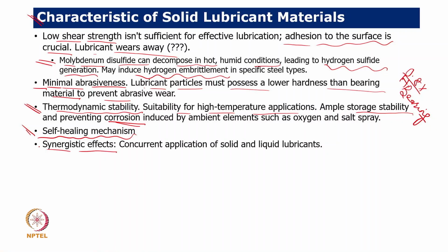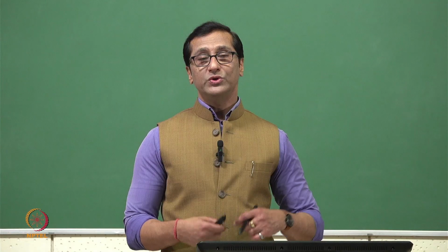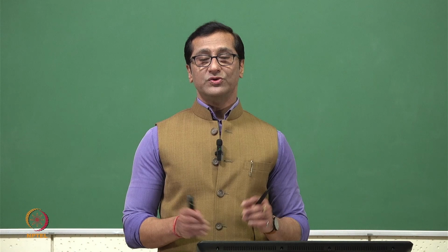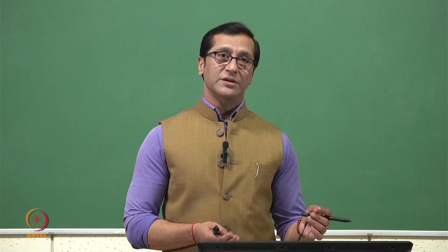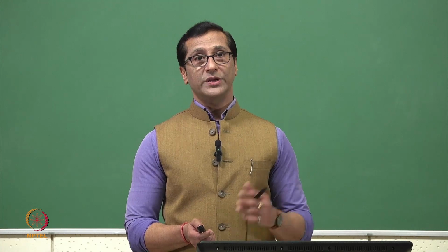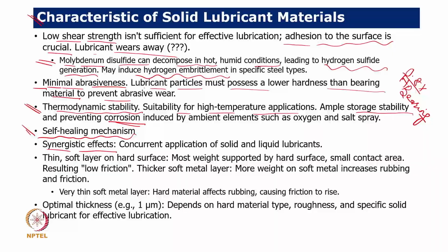One more point is the synergetic effect. If I am using a solid lubricant as well as a liquid lubricant, then there should be synergy. It should not happen that the liquid lubricant is reacting with the solid lubricant, or the solid lubricant is reacting with the liquid lubricant. So these are the important aspects.